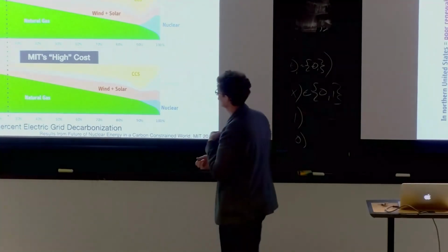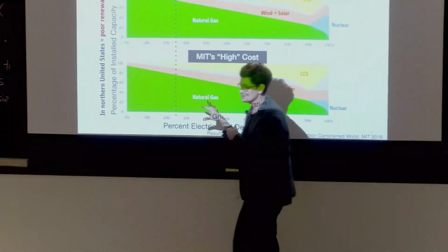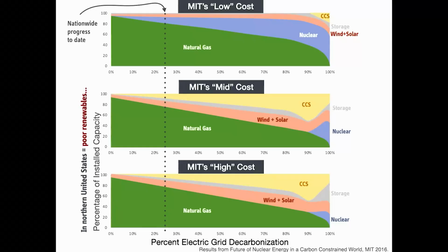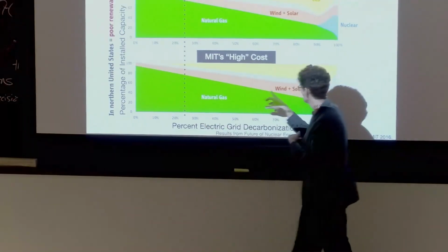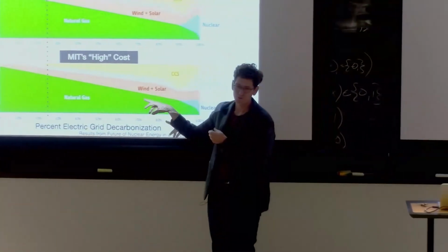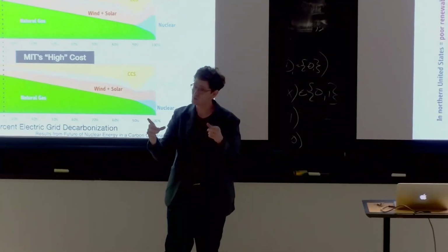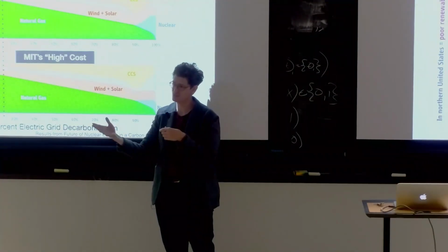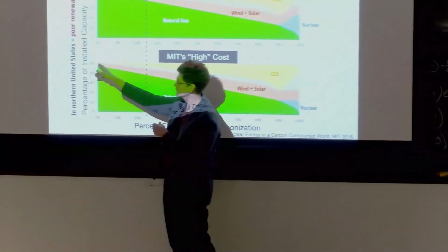Okay. So this shows you the fraction of total generation that should be partitioned by different mixes. So you'll see here, natural gas is dominant if you don't care about carbon. But actually, some wind and solar always gets built, because it turns out, even though it's not dispatchable, a little bit of solar that turns on in the middle of the day when the peak demand is highest is always going to be cheaper than paying for natural gas to do that. So even in a no decarbonization scenario, you have some wind and solar.